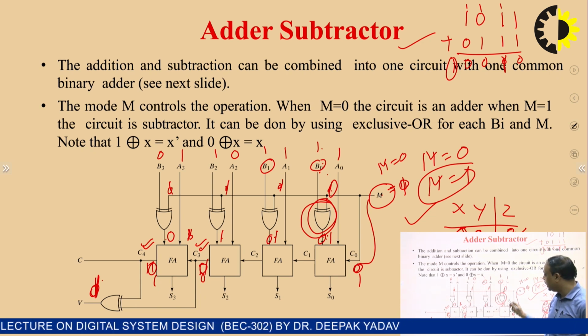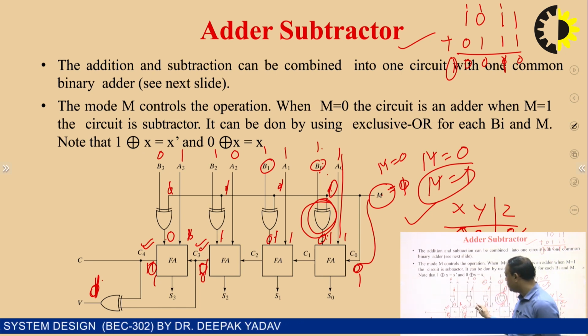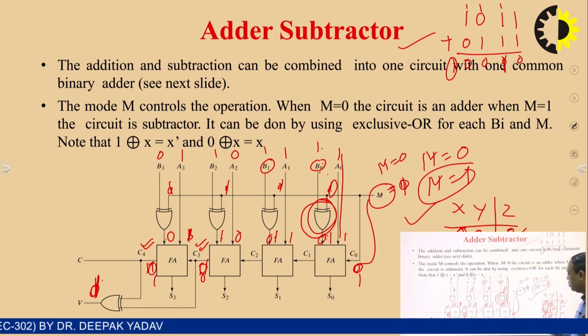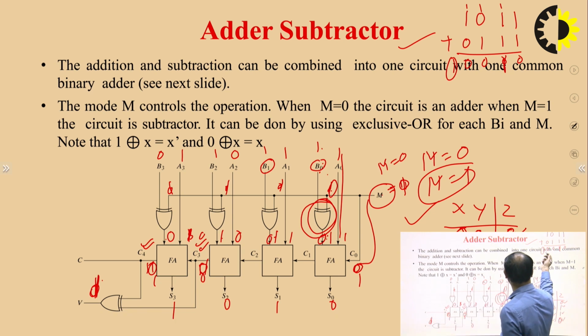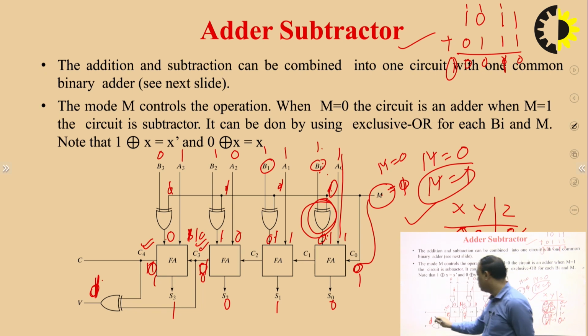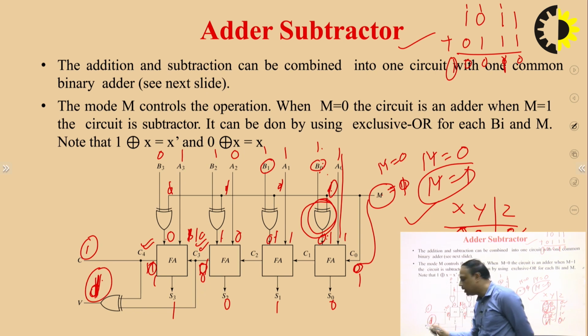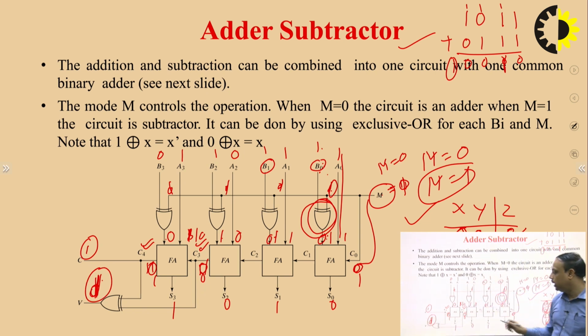Then with the help of the full adder circuit, this bit 1 comes here, this one over here, this one again over here, this becomes 0 and this becomes 1. And when this gets added, we get the output as 0 1 0 1, and there is no carry over here. So C3 is one carry over here, and we have the carry out over here as well. So carry out is reflected over here, and we have this 1 which represents that both carries became 1, and we have to check this for the overflow for the next coming bits.